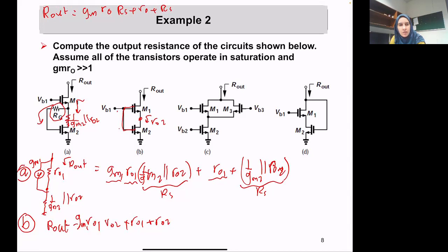In the previous class, I derived the impedance if RG was there. It is going to matter because there is a voltage drop across it, because ID is flowing there. So we have to be careful about the location of RG. Okay, now let's see example C. If anything still remains unclear from my answer, please let me know.